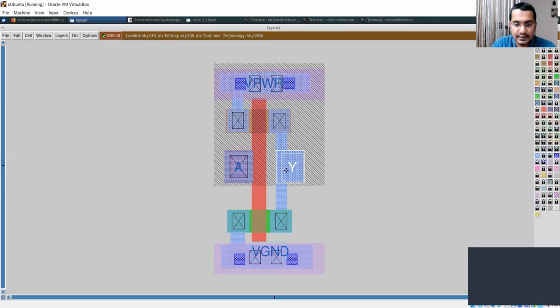So titanium nitride, so the question is, why titanium nitride? TiN acts as a very good adhesion layer for the SiO2. Okay, that's one of the reasons. And second, it acts as a very good barrier layer between the bottom levels or the bottom interconnects and the top interconnects. The next step is to deposit a blanket tungsten layer over here, and this will help us to create a very good contact from the bottom to the top.